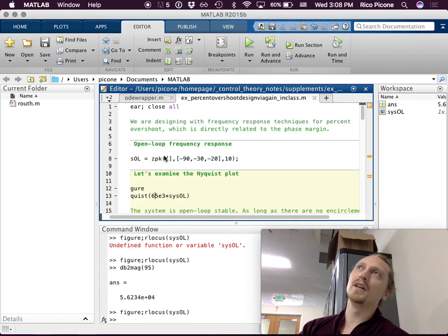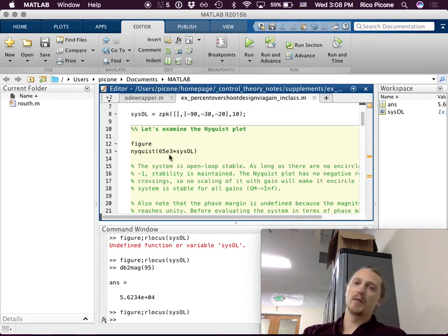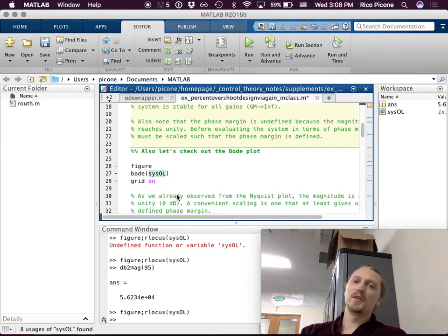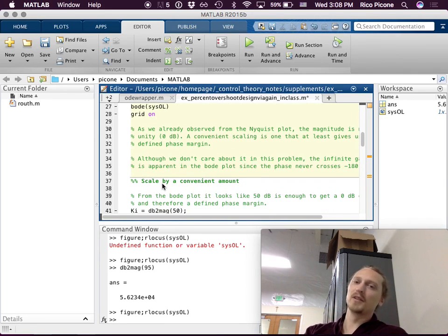And then we could continue the design that we are working on now. We could do the 20% overshoot design with this system as well, right? We would just have to make sure that we don't increase the gain too much. It'll be obvious if we do in our simulation. It'll be very obvious. But we don't expect to. It would be an accident if it happened, because we're shooting for a positive phase margin, right?